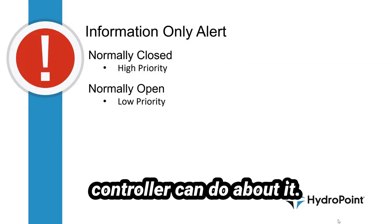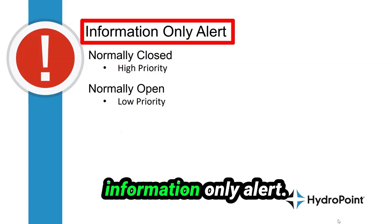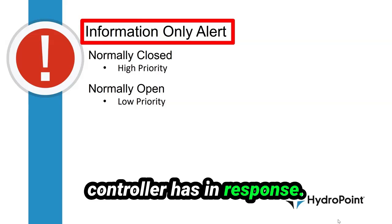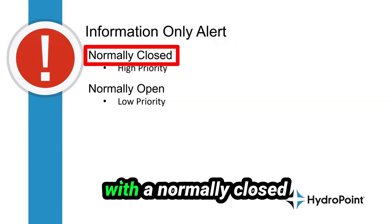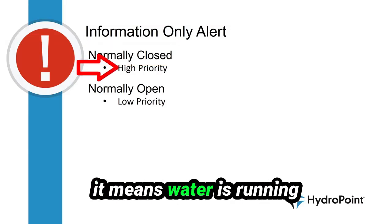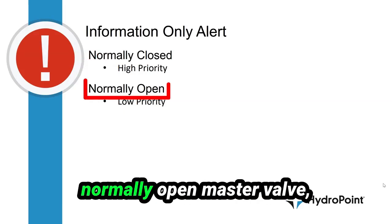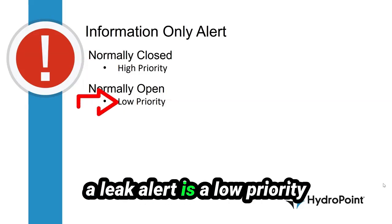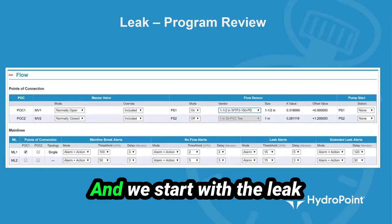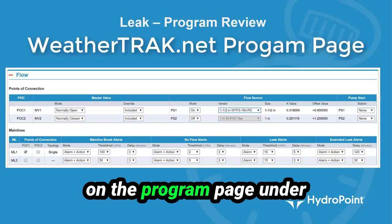Either way, there's nothing the controller can do about it, so it's important that a user knows that the leak is an information-only alert. There is no action that the controller has in response. So if you manage a system with a normally closed master valve, this can be a high priority alert because it means water is running in the field unchecked. However, if you manage a normally open master valve, a leak alert is a low priority alert because it's expected behavior on the system.